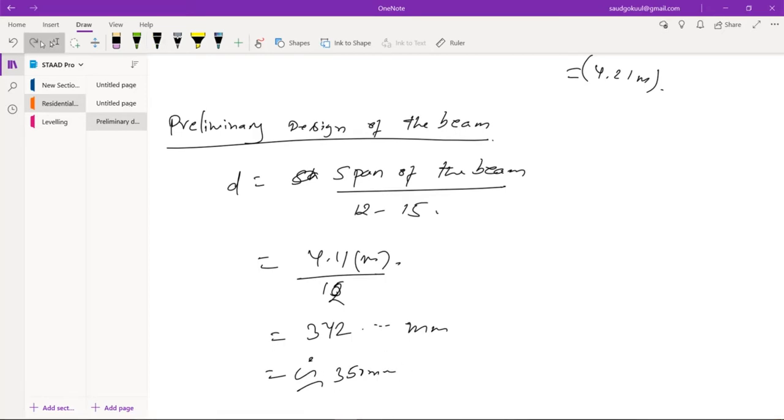One thing that I forgot to tell you in slab design is that we got the effective depth as D, and the overall depth, for both the slab and the beam, follows the same principle. The overall depth D is equal to the effective depth d plus half of the rebar plus the clear cover.